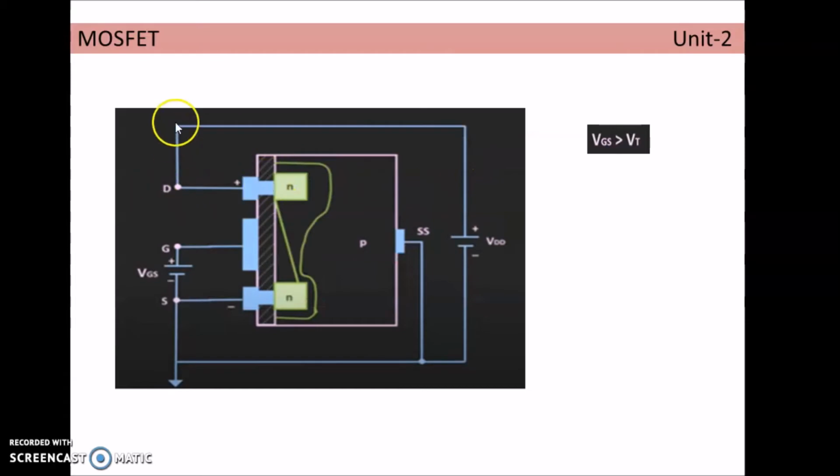Now if the drain source terminal voltage is applied, the electrons that are accumulating in this n region start to move freely towards the positive terminal of the battery, and as a result the current starts to flow in this direction. That means from the negative terminal of the battery towards the source, and again from the n region through this channel, this n region, and through the metallic contacts, the drain terminal, and again the circuit is getting closed like this.